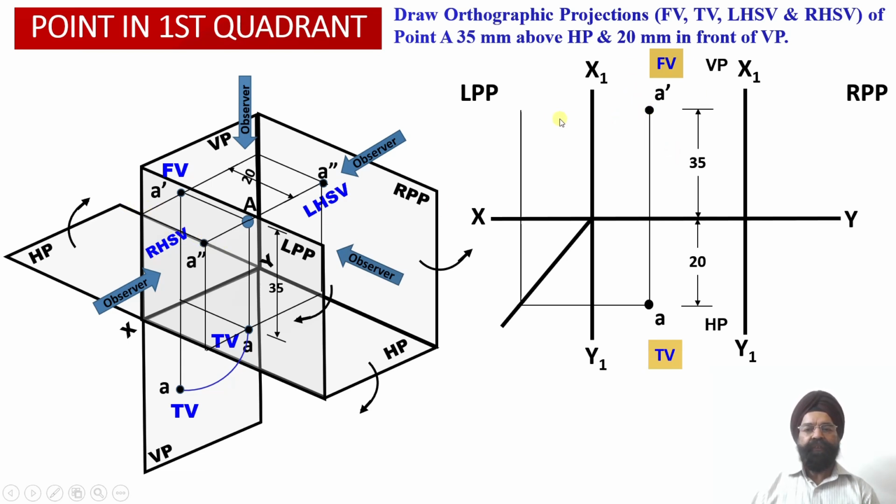So we will be able to obtain the right hand side view projection of this point A onto the left profile plane wherever the horizontal projector line drawn through point A dash into the left profile plane intersects with this projection line, which has been transferred into a vertical projector line. This intersection of these two projector lines provides the location of the point A double dash in the left profile plane.